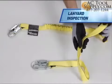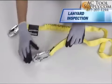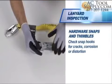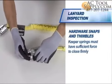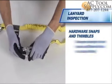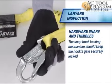When inspecting lanyards, work from one end to the other using a slow rotation. Check snap hooks for cracks, corrosion, or distortion. Keeper springs must have sufficient force to close firmly. The snap hook locking mechanism should keep the hook's gate securely locked.